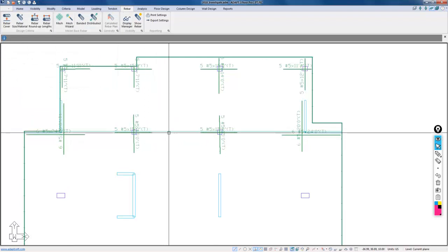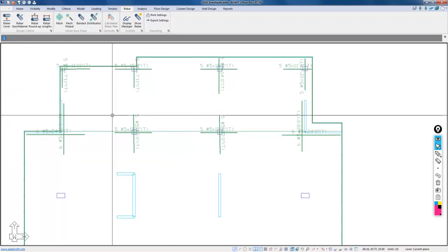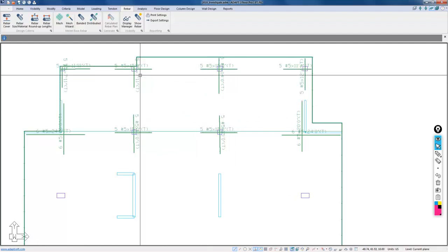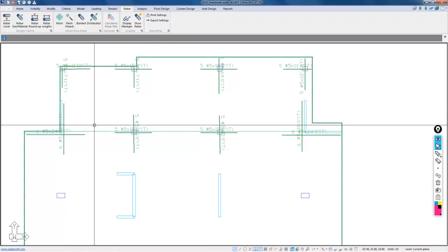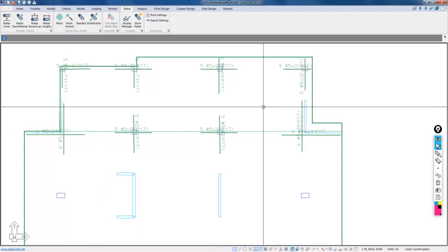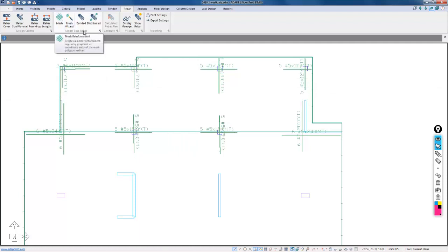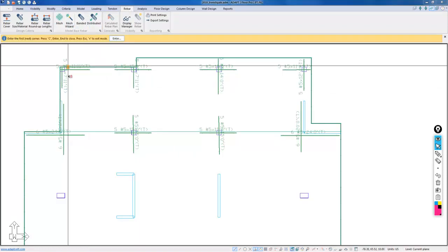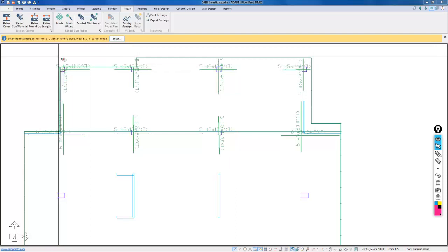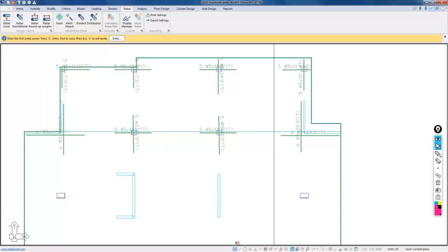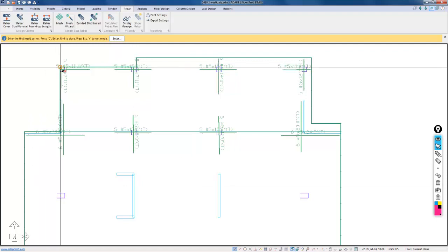Now in the bottom of the slab, we're going to assume that there's a number 5 by 18 inch on center mat of steel, in addition to some extra bars located in these outer bays in the slab. So we'll show that process. We're going to go to the model base rebar from the rebar ribbon and select mesh, and I'm just going to select the corners of the slab where I want the mesh. So we'll make sure I have only the endpoint snap option turned on.